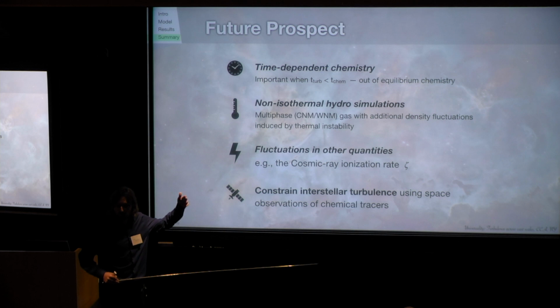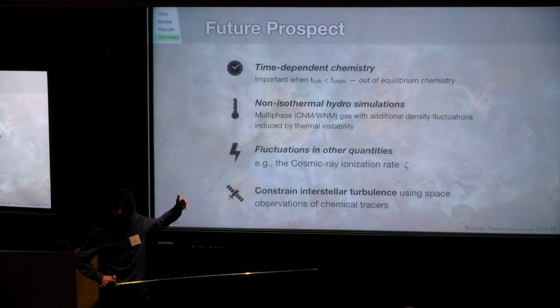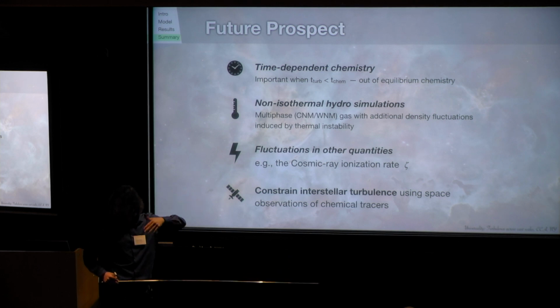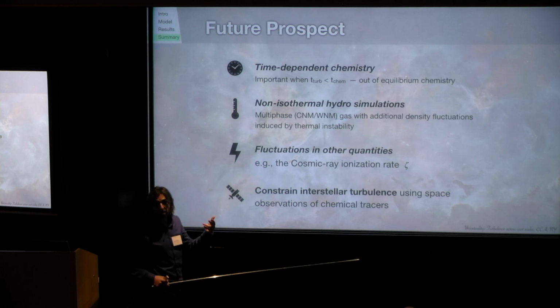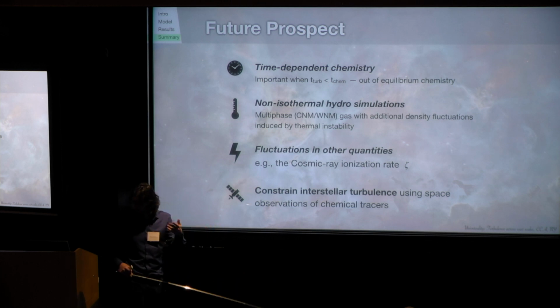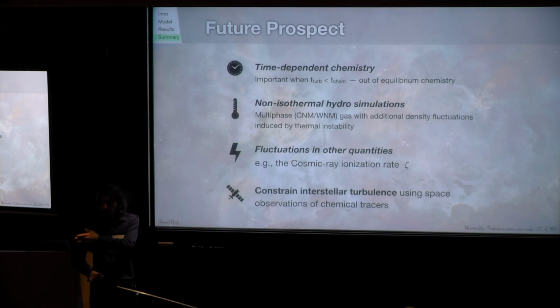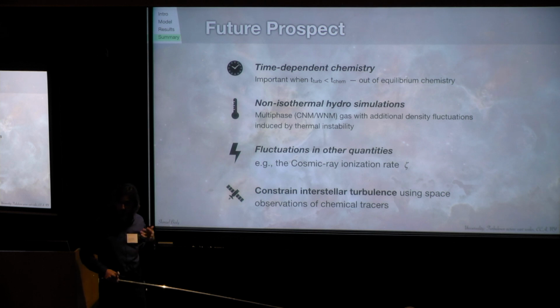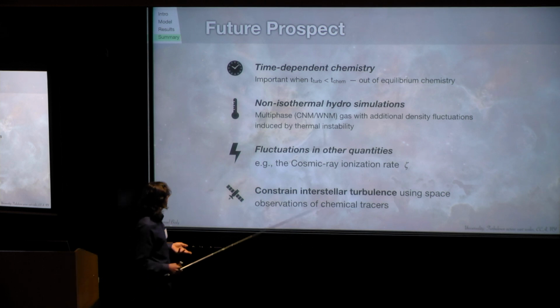In this model, we assumed chemical equilibrium. This might be a good assumption in some cases, but not always. Depending on the time scale of the turbulent motions, if it becomes short compared to the chemical reaction time scale, then the chemistry can be out of chemical equilibrium.